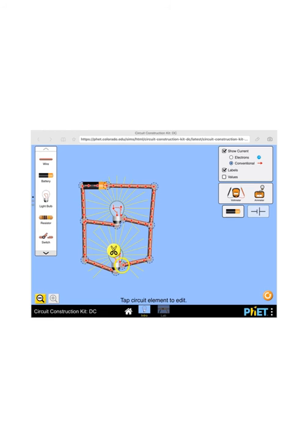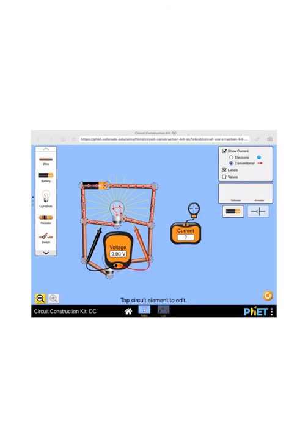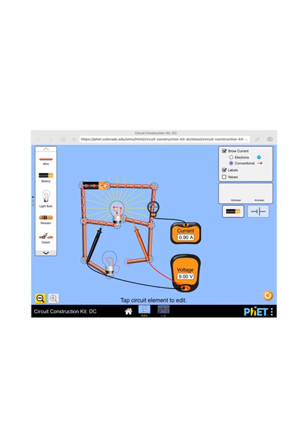If I disconnect the bottom one and measure voltage, here I'm using a 9-volt battery rather than a 1.5-volt battery and a 10 ohm light bulb again. And if I measure the current through this system, 0.9 amps, where there's a 9-volt difference across the single light bulb.